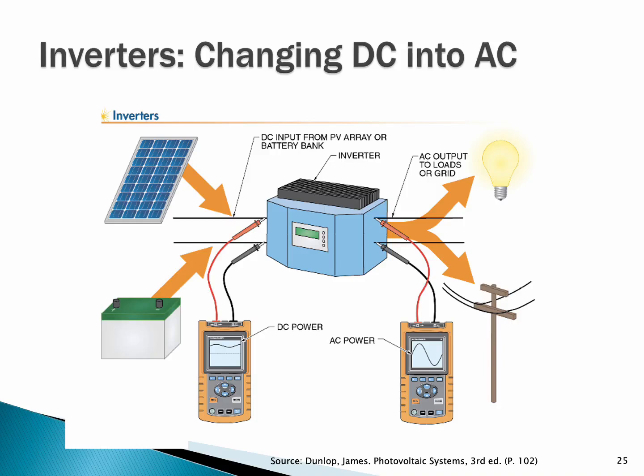So we have this DC made off of the array, and then we have an inverter which inverts that to usable AC. And in a minute we'll talk about how it does it, but it's based on transistors in high-speed switching that are going to create an artificial sine wave that's actually smoother and cleaner than what the utility can provide.